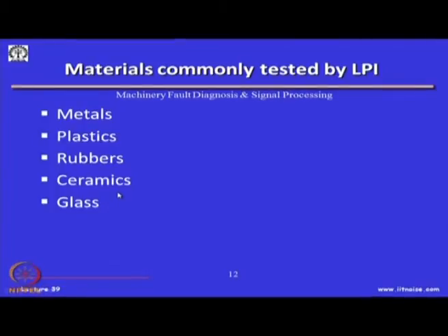There is no end to it, provided your liquid penetrant can actually seep into the cracks, and we can let it dwell and then ooze out, so that if there is a dye in that penetrant, it can glow under UV light, or I can apply a developer, so that this liquid is going to leave an impression on the developer.